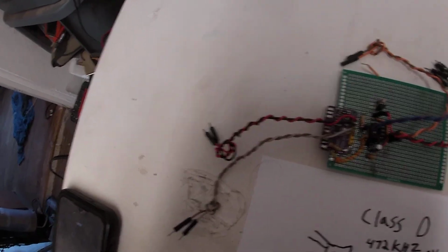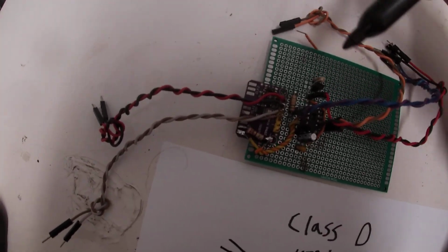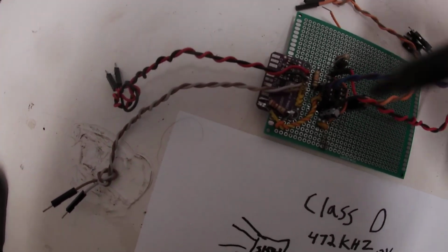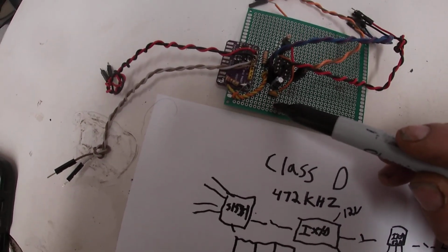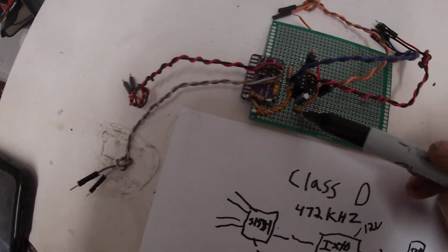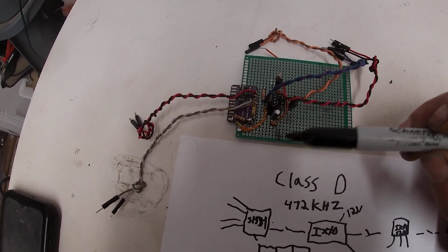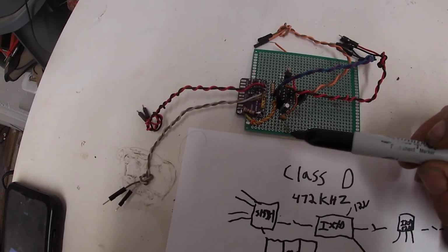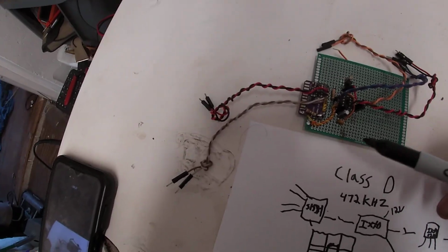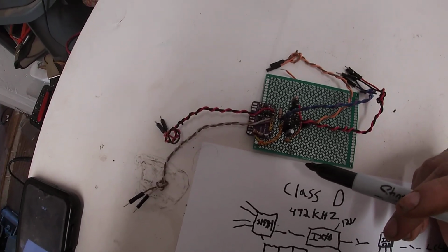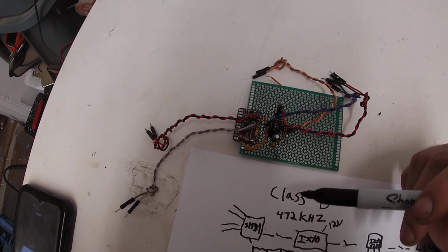And we'll touch it right now on, you might notice a few extra parts. All we've got are extra capacitors, electrolytics, and just normal ceramics. And all those are doing in this function is decoupling. Decoupling on the power side just makes everything quieter. And probably a few other things.